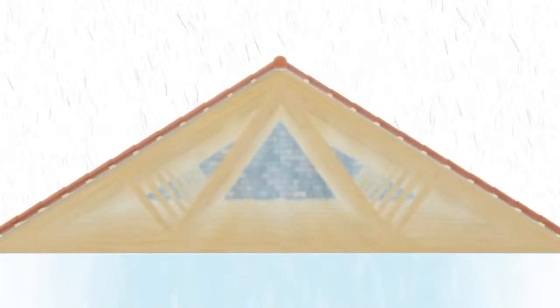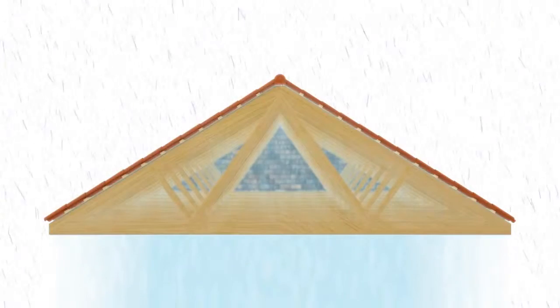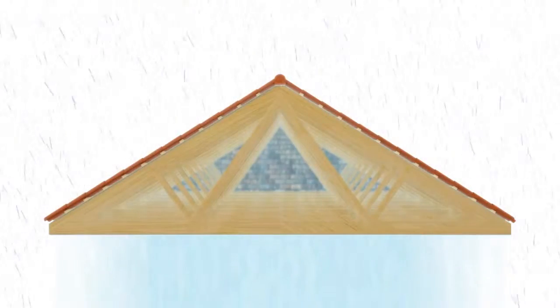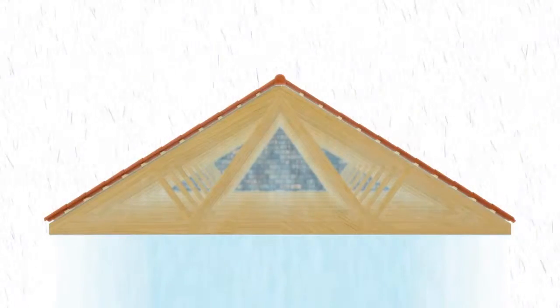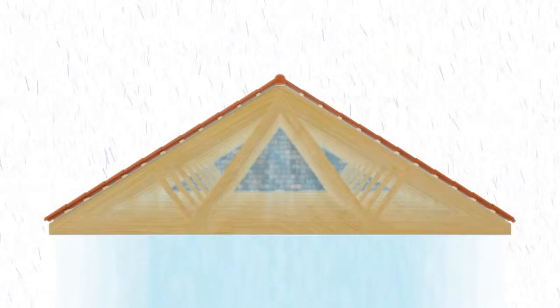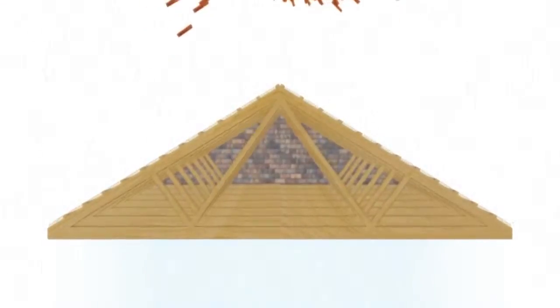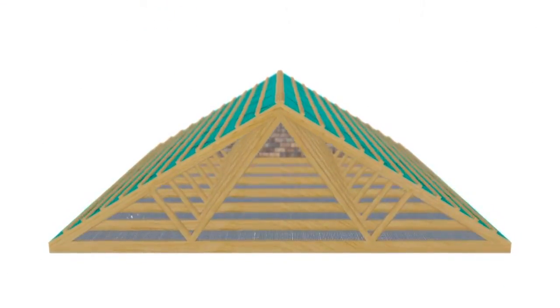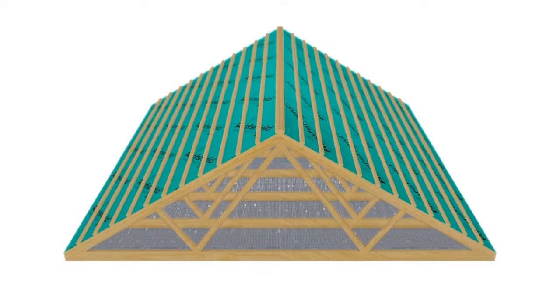There are two main types of moisture that roofs of all types must control: moisture from internal sources, vapour and condensation, and moisture from external sources, rain and snow. External moisture is assumed to be primarily dealt with by the external weatherproofing once the building is complete, but in order to provide a secondary layer of weather protection, roofs are fitted with an underlay membrane beneath this outer layer.